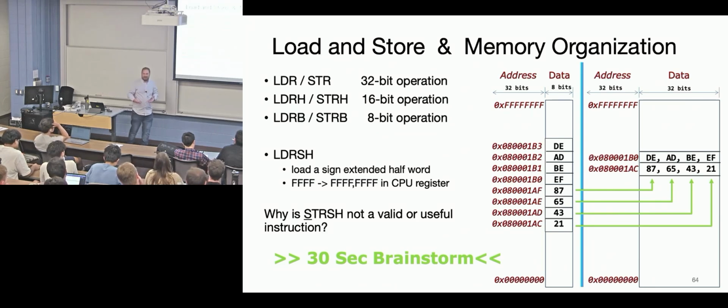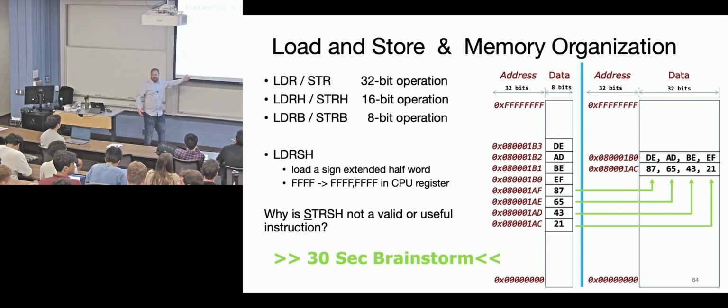There's no typecasting, right? So your SRAM does not care if it's signed or not signed. There's no idea about that. You as the programmer, or at least the compiler, has to keep track of that and say, oh, that thing I put in there, that's 2's complement. I got to go and treat that special. But the memory doesn't need to know anything about it. So telling it using a special instruction that stores it signed, memory doesn't care. Just give me bits. I put bits in there. That's all it does. How do you feel about that? Okay.